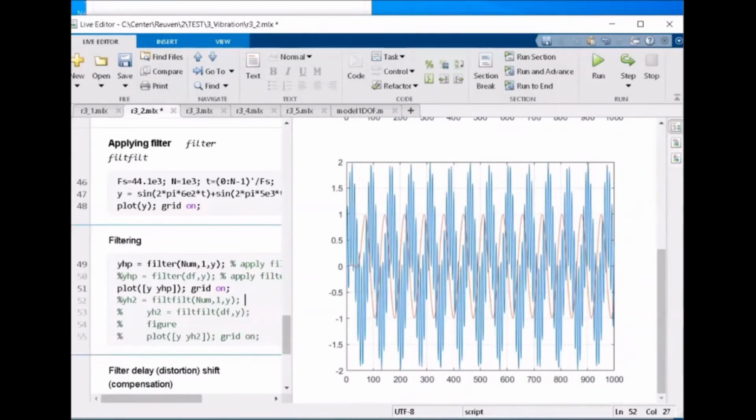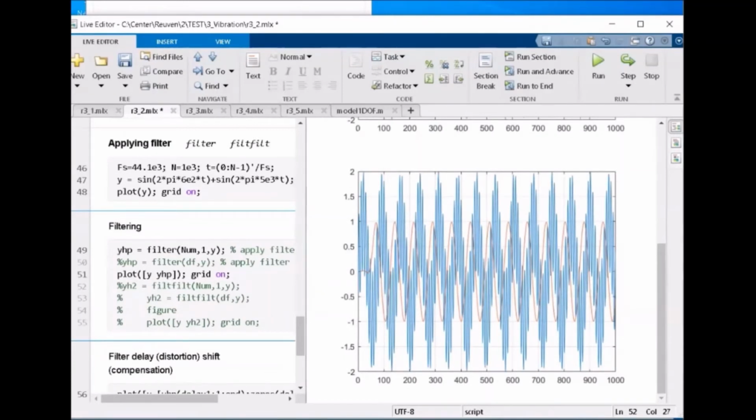You can see that using this low pass filter, we just throw out this high frequency harmonic and we will get our signal back. But can you see this is not exactly the same signal as it was? Anybody can tell me what is the difference? Time lag. Right, after applying the filter, you're absolutely right. We will get the lag, the shifting in time. Our filtered signal is shifted according to the initial signal.